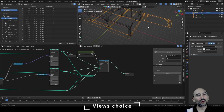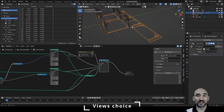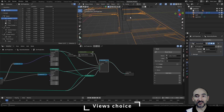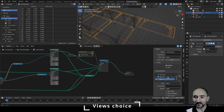But if we want more control in our export, maybe in a CAD format or whatever, it would be useful if we would add a new parameter to have an offset between these 2D projections, so a sort of space between these 2D projections. So we can go in the group input and go here after the menu that we can call views, because this is the view we want to have in the result, and add another parameter. We can call this views space.